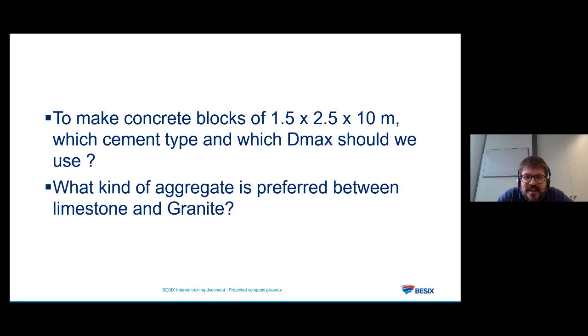Hey, can I answer? Yeah, sure. For the type of concrete, I think mixing of fly ash and GGBS can be good, because we can reduce the viscosity as you mentioned. On the other hand, we can use fly ash to reduce the bad workability of GGBS, and we can improve the durability of the specimens. I think. Yeah, that's really good actually.